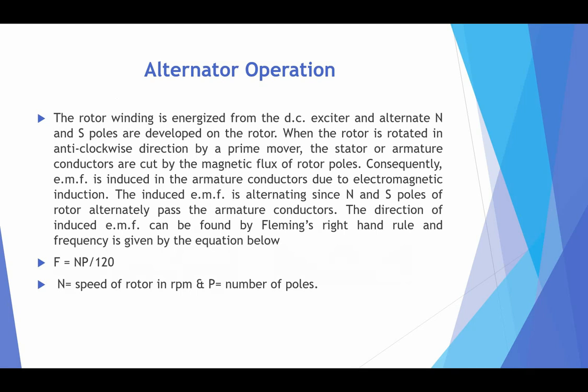It produces flux that, when rotating, cuts the stationary armature winding, and as it is rotating in nature, it changes with respect to the stationary winding. Hence, an EMF is induced in the stationary winding, and this is given to the load. This is the simple operation of an alternator.